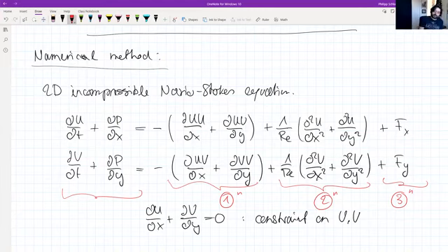As soon as we have 1, 2, and 3 together at the old time step, then we know what we have as a forcing, as a force to update the velocity. And that means then I can go into step 4, which is solving the coupled pressure and time. And actually, this will be the 2 independent steps. So I'll call them step 4 and 5 together. And this will then give me, in the end, the result at time step n plus 1. So this essentially is the broad view of how I would calculate it.